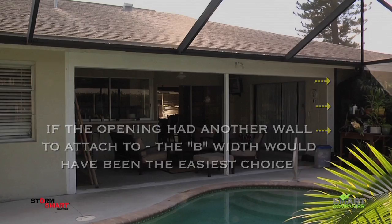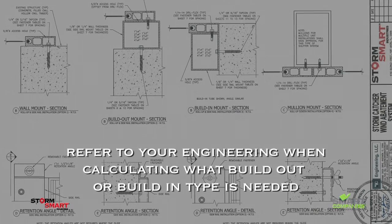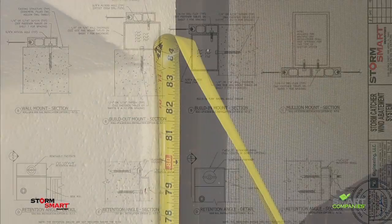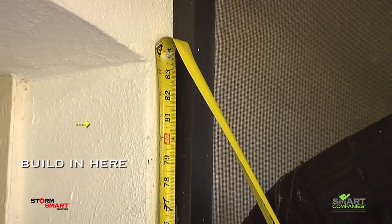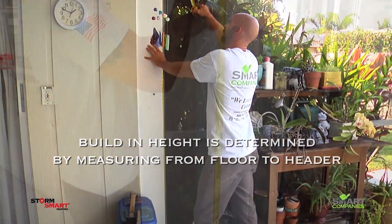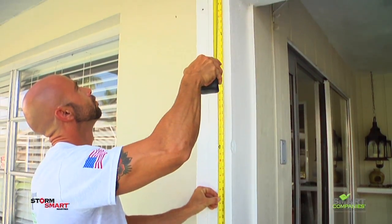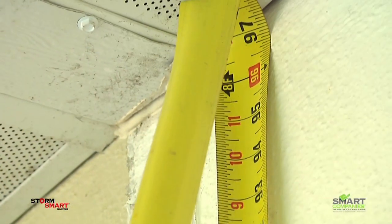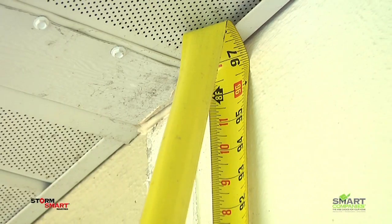In a situation like the one shown, you'll need to refer to your engineering to figure out the type of build-in needed. The height of the build-in will be from the bottom of the header to the floor. Next, measure the height of the opening. Because there is soffit here, it would be best to measure from the soffit to the ground and use that as your C, or overall height measurement.